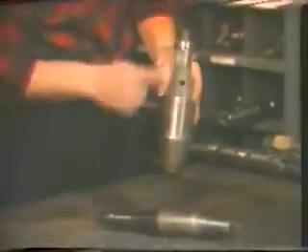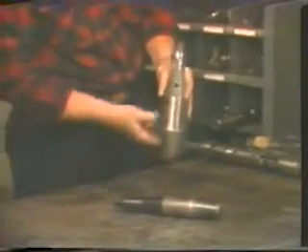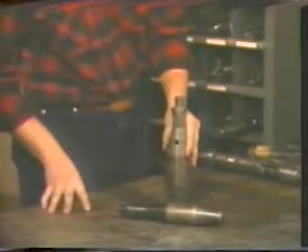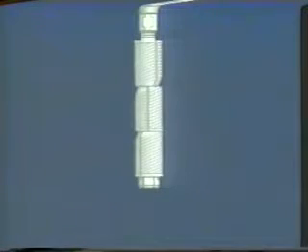The tubing swage can be used to open up constricted places in the tubing if they are not severe. This tool is tapered on both ends to allow the tool to be jarred through an obstruction repeatedly until the tubing ID is returned to normal. The tubing broach is also a tool designed to remove obstructions in the tubing wall. It is particularly useful for removing metal burrs from tubing ends that may have been damaged while tubing was being run during completion. The primary difference between the broach and the swage is the swage does not remove metal from the inside surface of the tubing, and the broach does actually shave metal away from the tubing.